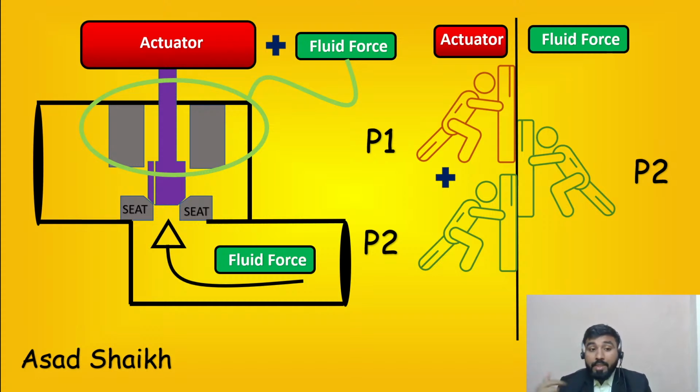First thing. Second thing is, if you can see my mouse here, once the fluid enters at this particular point, there is going to be another leakage path available. So your leakage chances also increase. So again you need to be very cautious: are you okay to have a slight amount of leakage here?